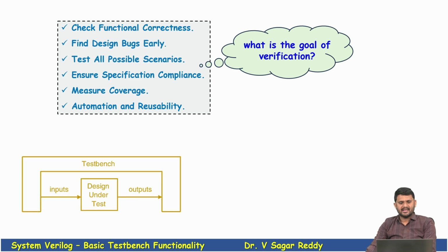A test bench is a virtual testing environment created in SystemVerilog or Verilog to verify, validate, and ensure that the DUT behaves correctly under all possible scenarios, before it's synthesized or implemented on hardware. Reusability is one more important aspect here. We can reuse the same test bench for multiple designs and also for configurations.